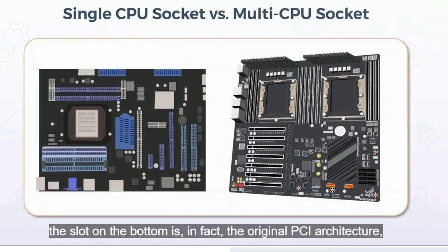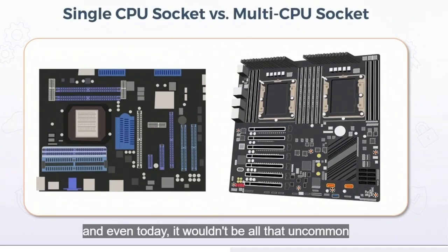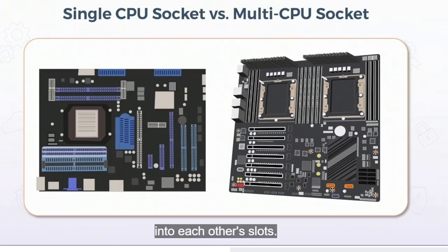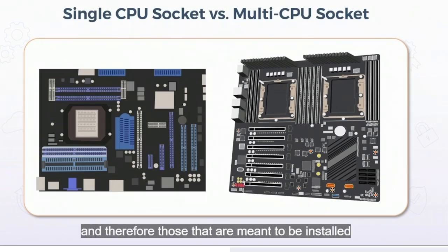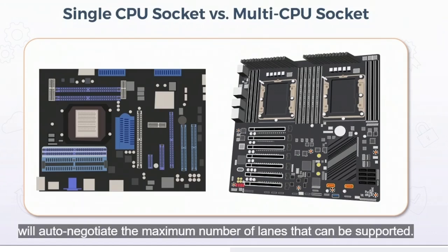Another consideration is the physical number of sockets that are present. Motherboards commonly designed for network servers or maybe even higher-end desktop systems offer multi-processor models, which of course can dramatically increase the workload that can be handled by that system. Now, while modern processors do have multiple processing cores, that's not the same thing as having two or more distinct physical processors. So if, for example, your current system has a single quad-core processor, there aren't actually four separate chips. It's just a single chip with more processing capabilities than a single-core processor. But with two physical sockets, you could install a second quad-core processor, effectively doubling your overall processing power.